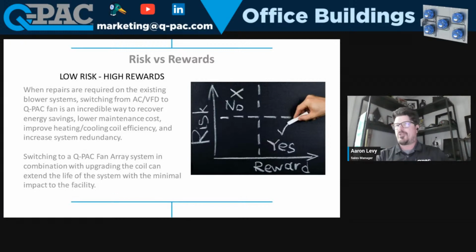One of the things that people talk about with EC fans is harmonics. And the big key when we talk about those things is the differences in the drives that we're replacing. The inherent differences in some of them are no different than comparing a 12 or an 18 pulse drive to a 6 pulse VFD. They're drastically different in how they handle certain harmonics and how they handle electricity. So they're not always apples to apples. When we have those issues, we know where that conversation starts and how we can work with our partners to do that.